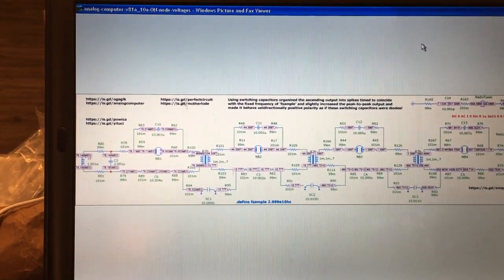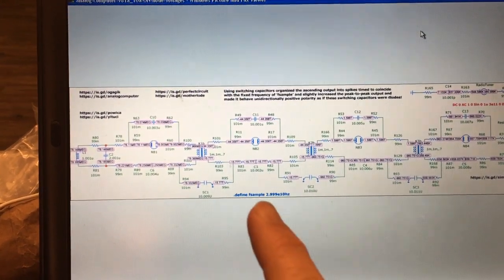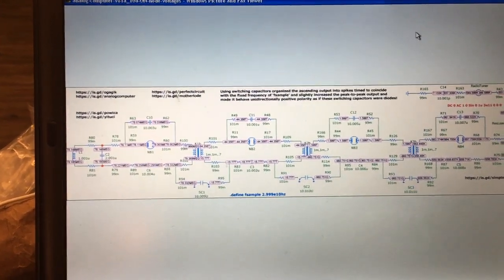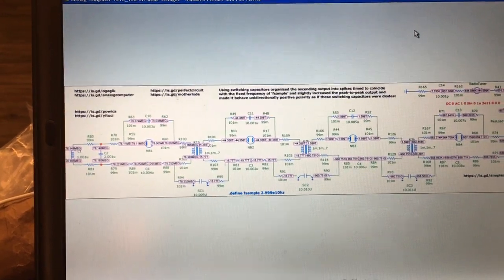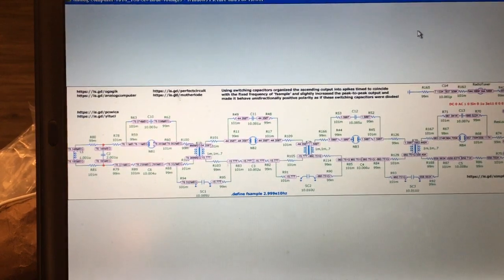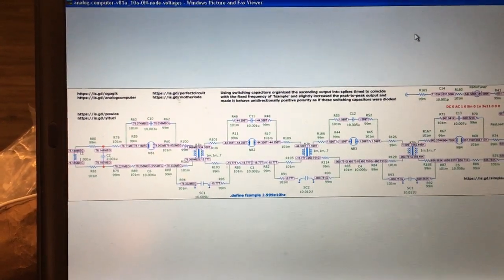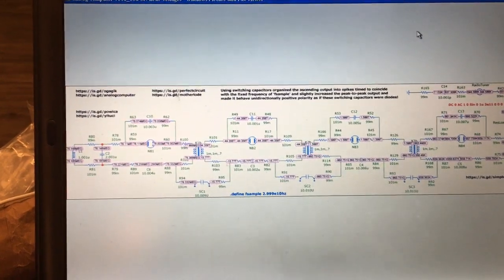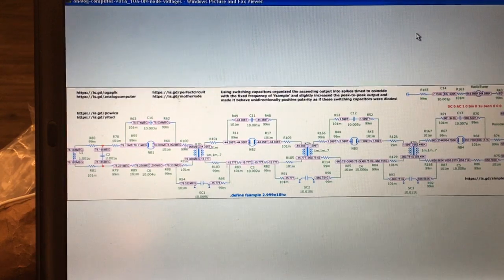And the sample time, or F sample in this case, which I'll get to in a minute, is down here. I customized it for all 3. That's your total cycle time, and then it's a 50% duty cycle within that cycle time that you ground or not ground the capacitor. Now you ground both ends, and the grounding procedure is done through resistors.